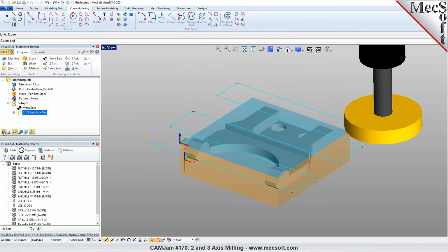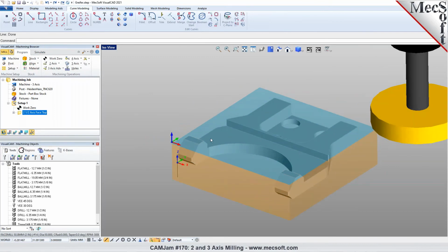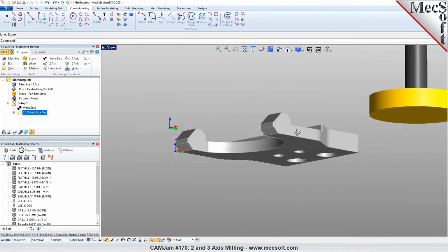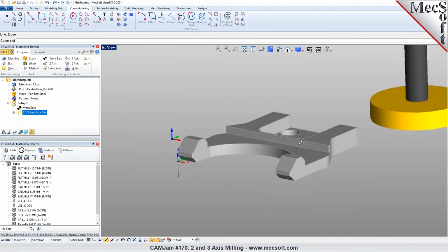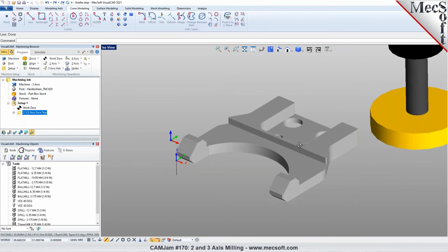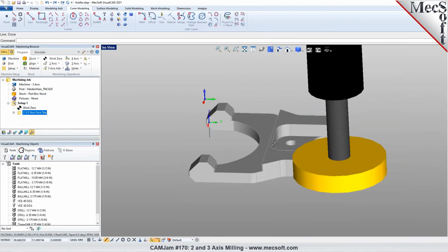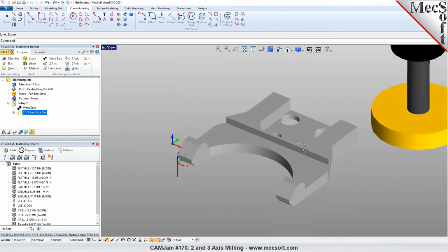The next step is we want to go ahead and program the toolpath. So you probably want to pocket these areas out, right? Yeah. Remove material. Now there's multiple different ways you can do it. Since these are at different elevations, you could program them using 2.5D milling, or you could use a 3-axis milling strategy, depending on how you want to program this. If you want to have more control, you want to do it step by step, you can do 2.5D operations.